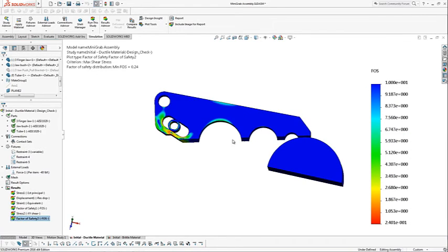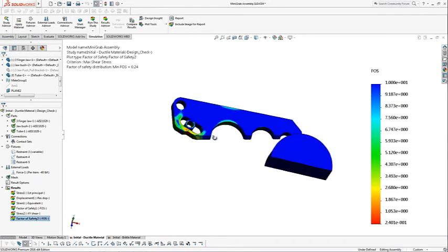And if we're really only interested in the results in that finger, you've got to be careful when you're interpreting results, right? This is not meant to be the simulation set-up series on looking at results, but just be aware, in situations where I'm most interested in looking at an individual part, it's always good to look at the overall stress state in the whole model. But I always like to create displacement, stress, and factor of safety plots for the specific body that I'm interested in. And that's kind of what I do.